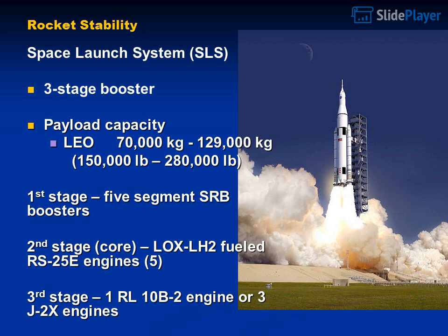First stage, 5-segment SRB boosters. Second stage, core, LOX LH2 fueled RS-25E engines, 5. Third stage, 1 RL-10B2 engine or 3 J-2X engines.